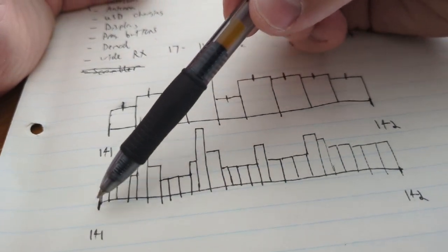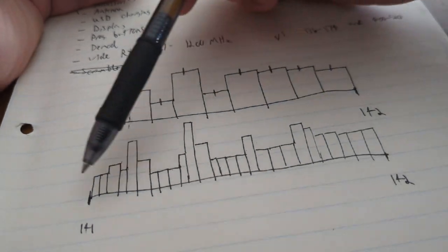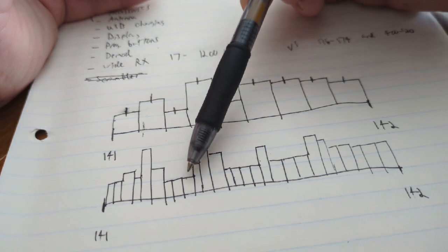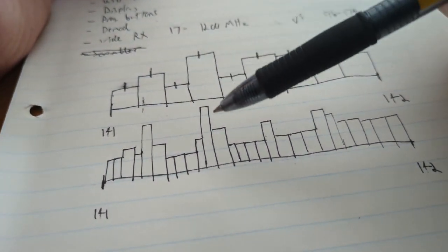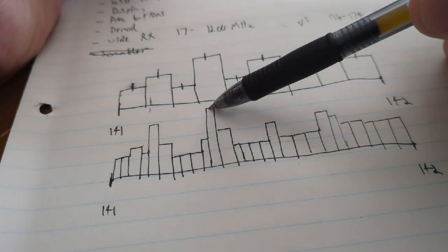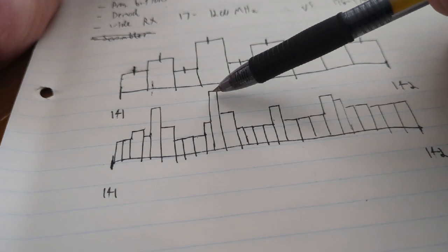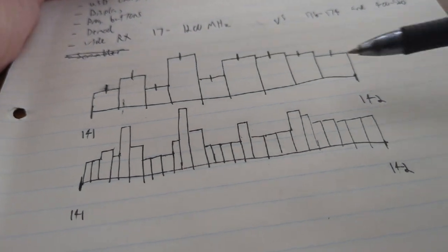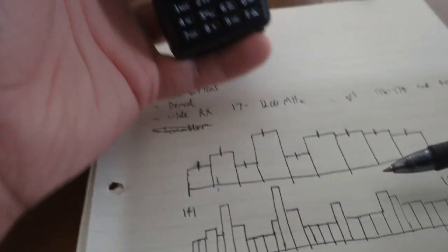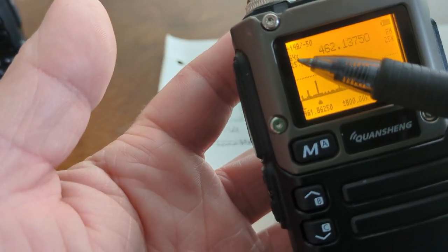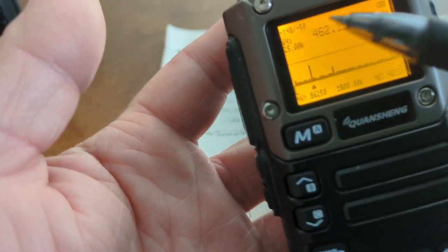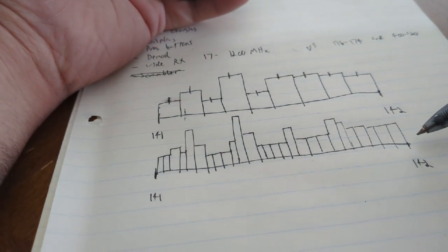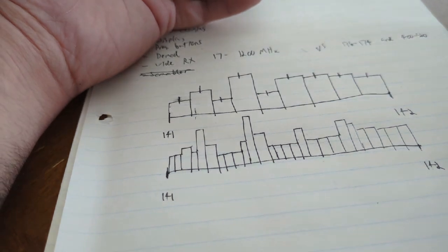If I want to get more specific into that same 141 to 142 megahertz, I could increase my number of bins, and I'll get a much more detailed view and see much finer-grained signals, and each one will be much more specific as to where that exact frequency is. I'll probably be closer to dead on in tuning, but this is going to take 3 times as long per sweep. So you're adjusting the number of bins and the width of those bins to compromise between how much of the radio spectrum you want to listen to versus how fast you want that scan to be.